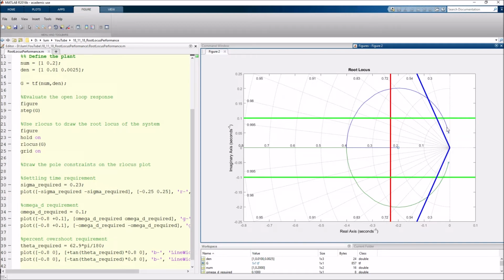So what we can easily see here, and what's really cool about the rlocus command, is that I can just click on the root locus, like right here, and hold. You see that I get a little cursor that I can drag around. So down here, this is the open loop poles. I got a horrible response, right? We saw earlier that was 600 seconds of settling time, and it was ridiculous. But as I start increasing the gain K here, you can see that value going up.